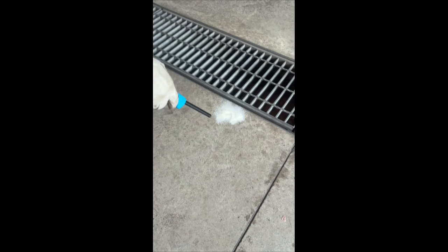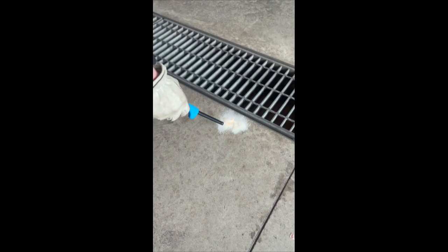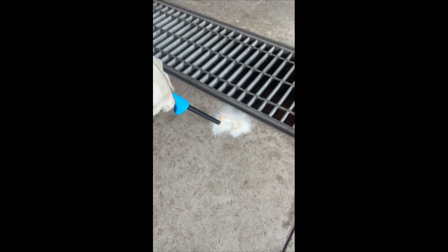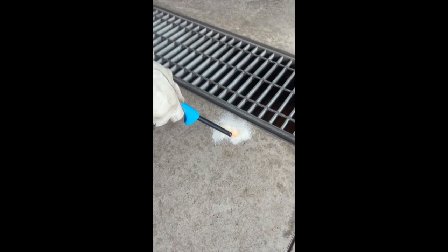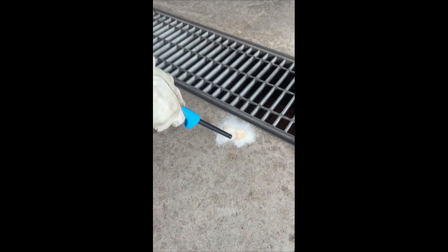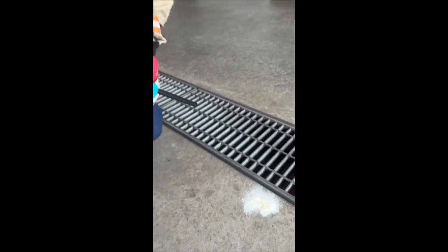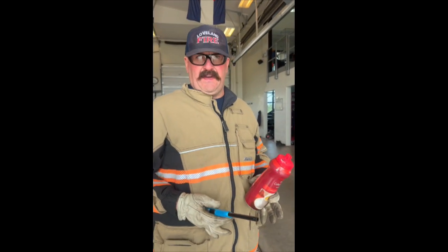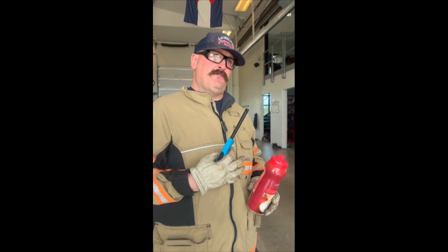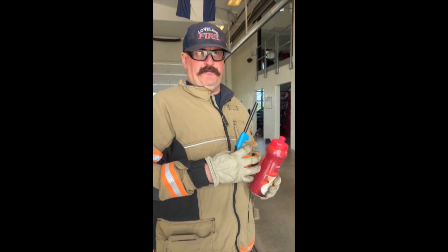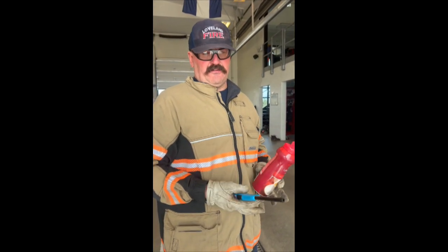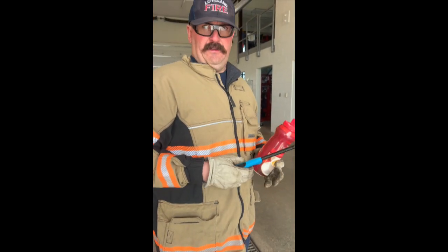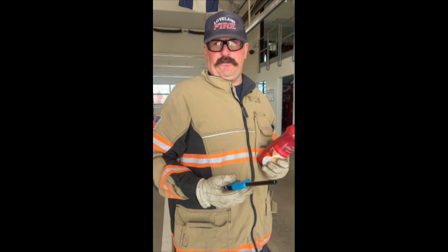If this was in our tank, it's our dry powder product, it doesn't burn. We may get a little bit of charring, but it doesn't burn, nothing that causes a hazard for us. Now, if we change the makeup of that into a finer dust, even though it's still a solid particle, now the fuel is more readily mixed with the oxygen, we'll get a different result. And again, this is only if you have heat or an ignition source applied.